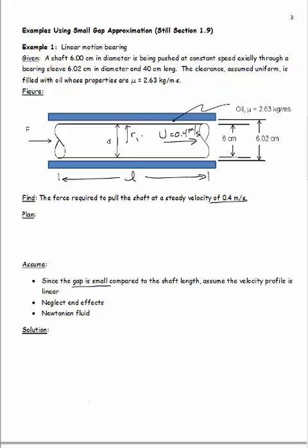All right, so what we want to do in these things, we're trying to find a force. So normally if you're trying to find a force or a moment, you want to write your stuff from statics. You want to start with a free body diagram, and you could have drawn it up here. It's kind of hard with the tightness of that shaft there with a small gap. So we have this force, that's what we're trying to find, and we know the sum of the forces equals 0.